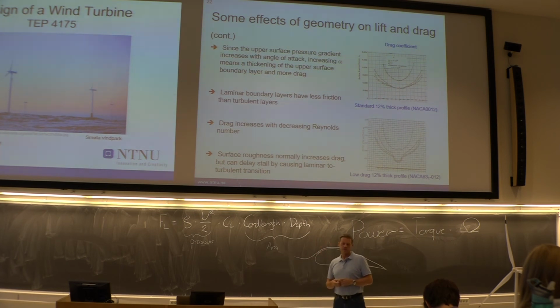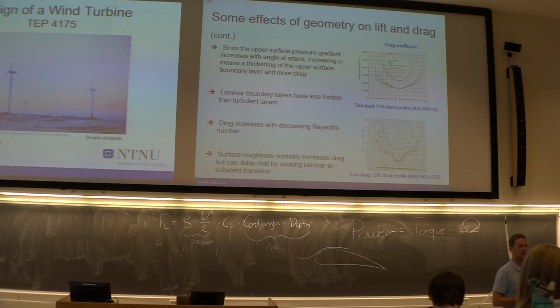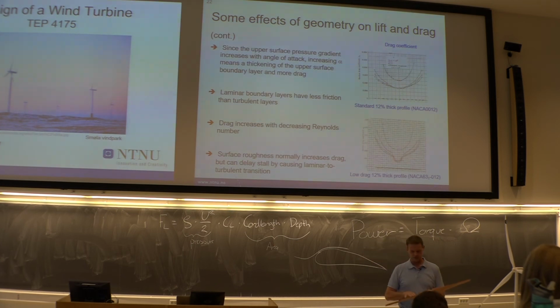And that is also one of the big uncertainties when we go into the wind tunnel. You guys will also be close to the laminar range of the turbine. So if you're spending too much time trying to polish it too much, that transition point might be in a different place than expected. And that will actually lower the efficiency.